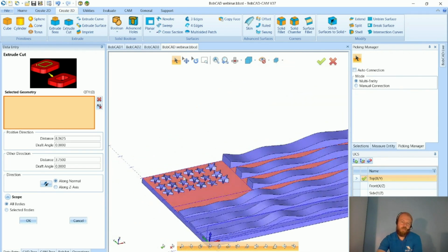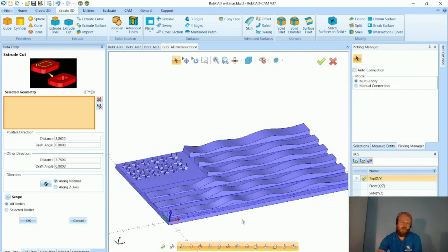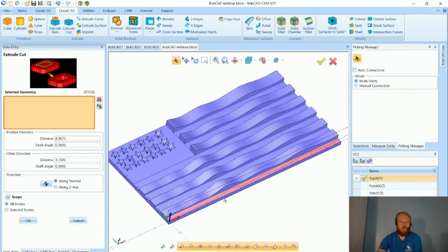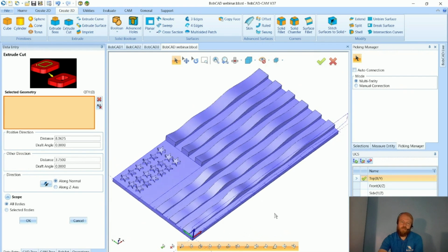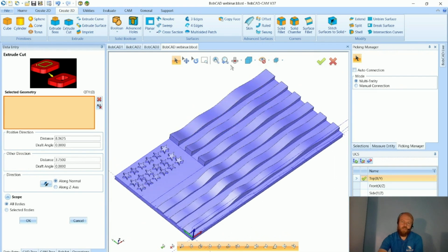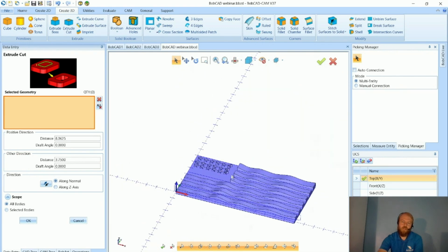That's what you would have to do. You'd have to do an extrude curve and do 2 separate solids, sort of like doing an inlay, I guess, in terms of CAD. But that's what you would do. That's how you would get some curves to your 3D model there.